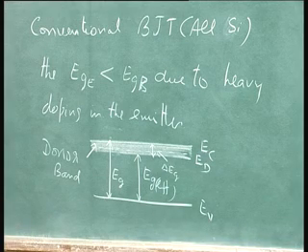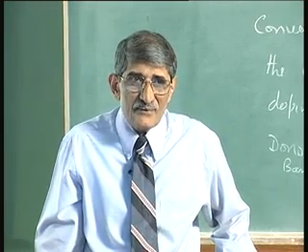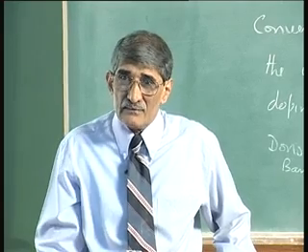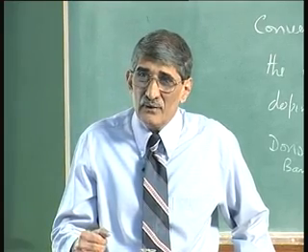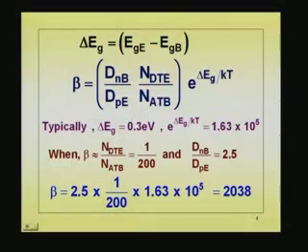In fact, if you switch over to a heterojunction, you will have the band gap in the emitter larger, and also you can go down to lower doping concentrations. So, you do not have that narrowing effect at the emitter. If at all, you may have the narrowing effect in the base, because you may go to higher doping concentration. So, you will have the band gap difference even more augmented. So, in the heterojunction, you have got this quantity positive, and we just saw.